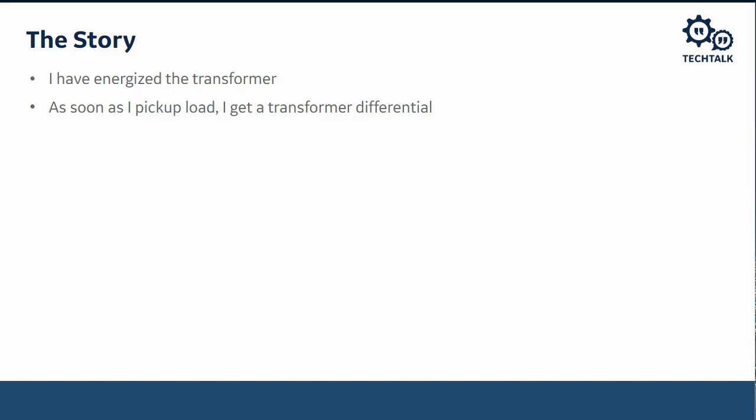My colleague Dan Ransom did a great tech talk on that particular subject, just on transformer inrush and how to restrain for it, and that's on our resources page. But in this particular event, they've energized the transformer. Transformer's been energized for some time, but they don't trip until they pick up load, and they do trip on transformer differential.